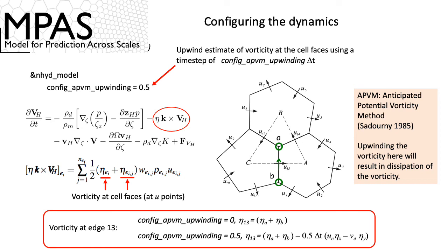And essentially what it's doing is it's dissipating entropy. Entropy is the mean square vorticity, and it's appropriate to dissipate entropy, particularly at large scales where the flow is characterized by a downscale entropy cascade. If you don't include dissipation that affects mean squared vorticity, this affects entropy, it piles up at the small scales, at the fine wave numbers, and you get a noisy solution.